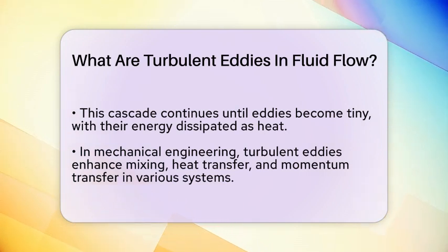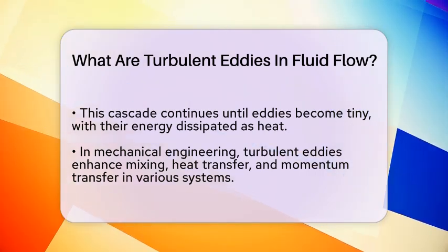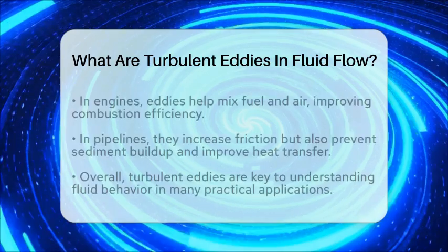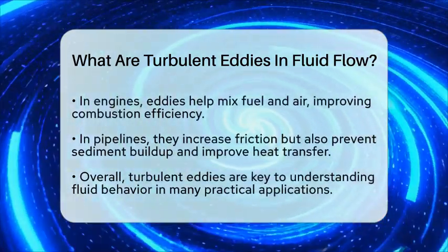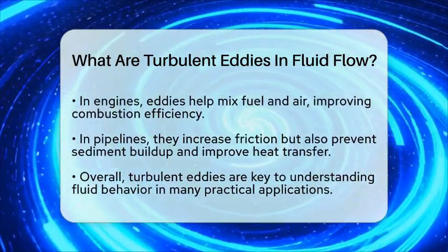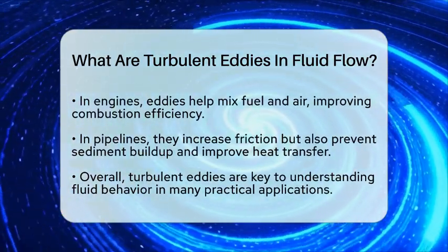In mechanical engineering, turbulent eddies are very important because they improve mixing of fluids and boost transfer of heat and momentum. For example, in engines, eddies help mix fuel and air more thoroughly, leading to better combustion. In pipelines, they increase friction but also prevent sediment buildup and help transfer heat more efficiently.